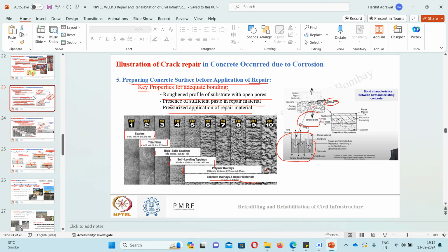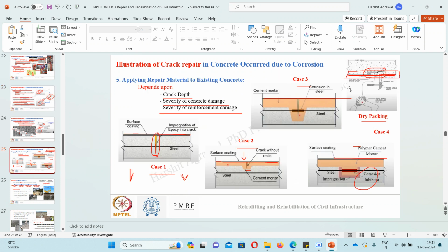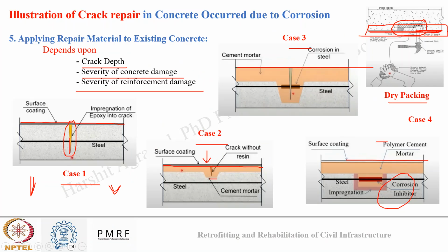So we can basically tie the reinforcement in the affected area which has been damaged. Suppose like in this image, suppose my rebar is like this. I can spot a location where severe pitting damage has occurred, and I know that this can be very critical now for tensile failure.